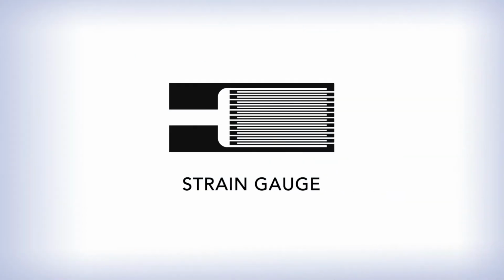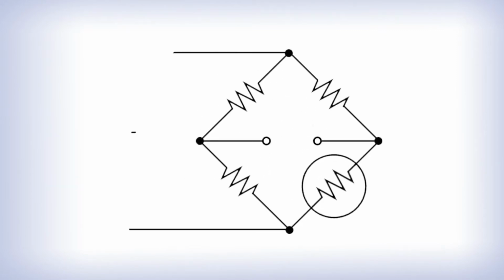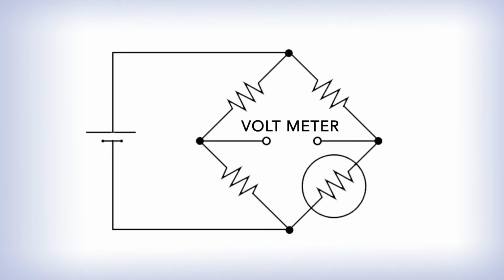The strain gauge is essentially a resistor that changes value due to an applied mechanical strain. The resistance change will depend on the strain applied and the gauge factor of the sensor. Since the change in resistance is typically a very small value, a Wheatstone bridge is used to measure it accurately.